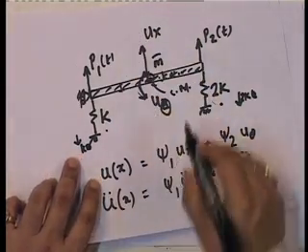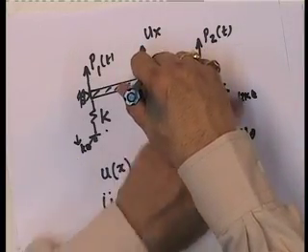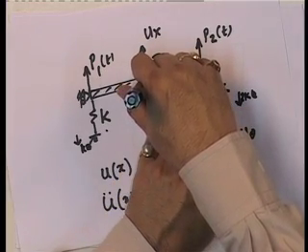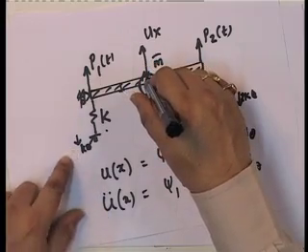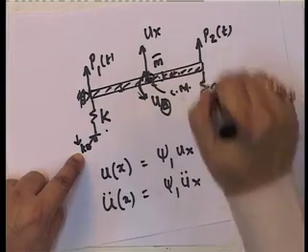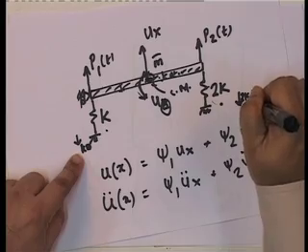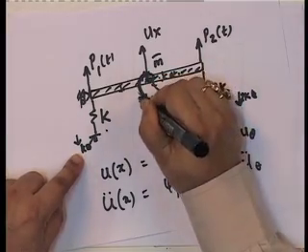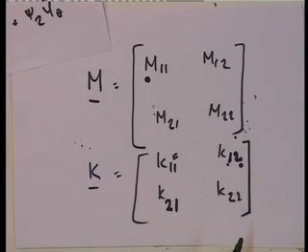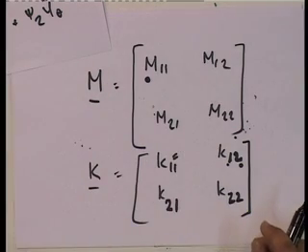So, let us look at the moment. Let us take moments about this point. What do I get? I get this way anticlockwise 2K into L by 2, that is KL, and here this is counterclockwise KL by 2. So, that means the net clockwise moment applied is equal to KL by 2. So, that means the equivalent load over here is equal to KL by 2. Note, this is something very interesting, and similarly you can do 2 versus 2, there is no problem.